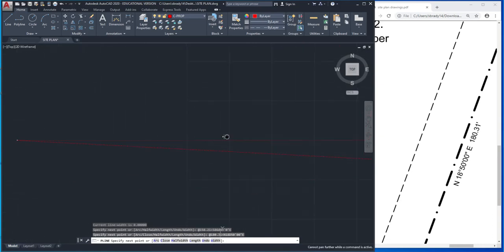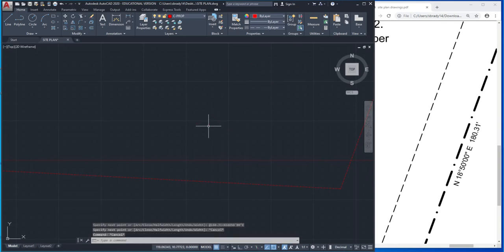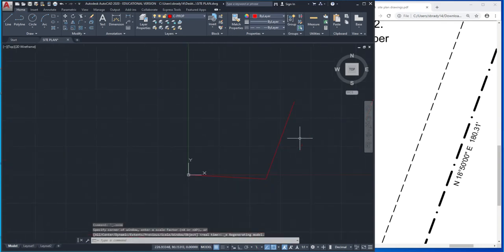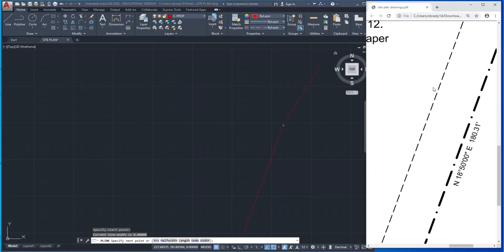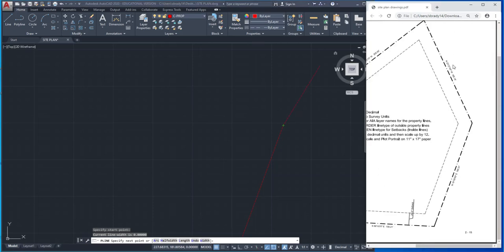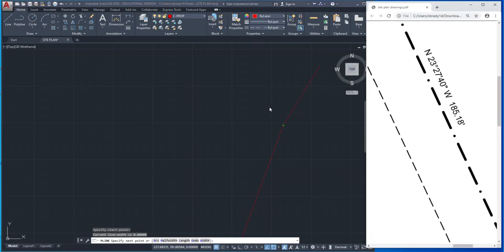It's constraining, likely because this is a pretty big shape. So I think I might have to hit escape to get my next input to be on my screen. So I have to hit escape, zoom extents, zoom out a little, and I have to restart my polyline. So I'm going to come up here to polyline, click, zoom into that endpoint, get my endpoint snap to engage, click, and I can continue on, okay? Now I'm going to find my third input here. All right.